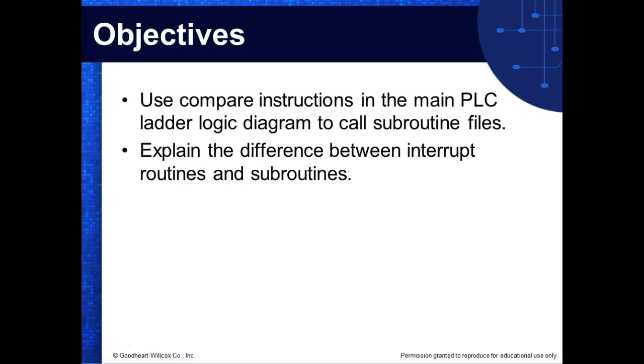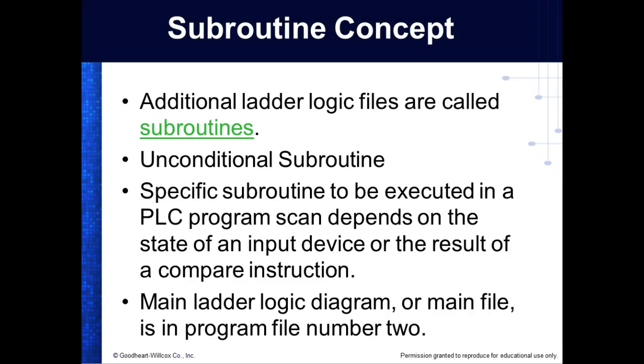And then, of course, in this section, we're going to also look at interrupts. It says specific subroutines can be called. When we do a jump instruction, we can have conditional or unconditional jumps, but we jump inside a program, or inside a ladder.